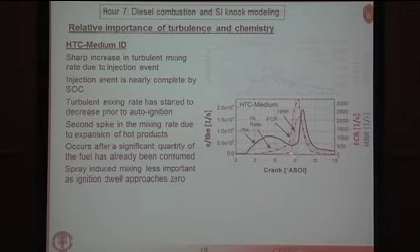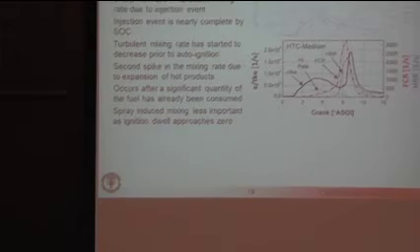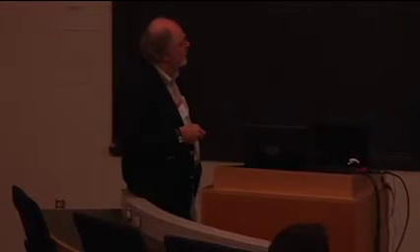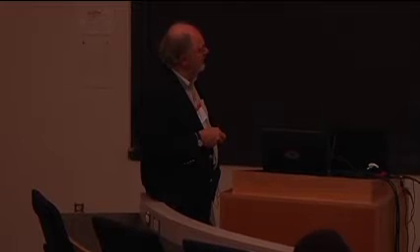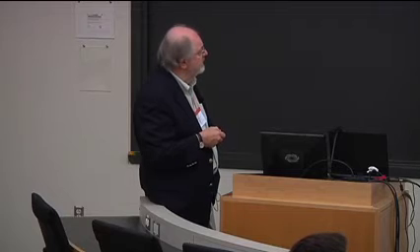The blue curve here shows the heat release. So basically, at a certain moment near the end of injection, we start combustion. Again, the FCR is the fuel consumption rate. You see we're forming those low temperature products, but they don't release much in the way of energy. And then, as I said, we see this sudden onset of ignition. And notice what happens to the turbulence here. Big increase associated with the combustion event.